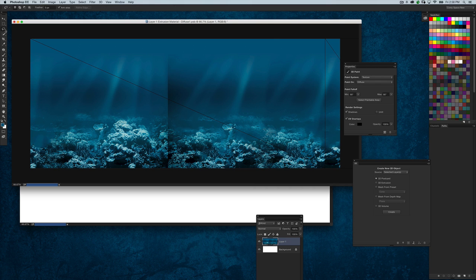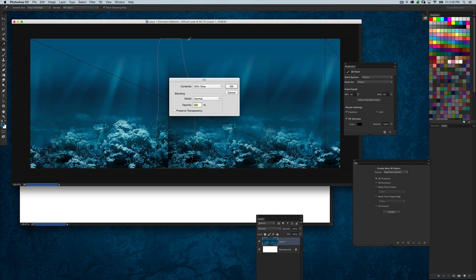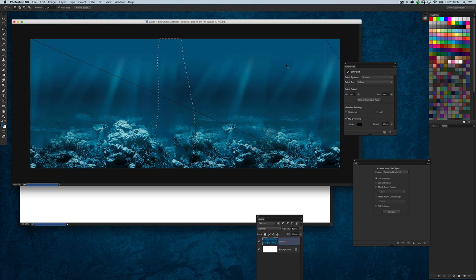So all we're going to do with that is just simply select that little area. And we'll just do a simple content-aware fill. And that gives us that little bit of the blend in there. Now you could go ahead and take the patch tool like we did a while ago and just modify it further if you wanted to. Just add a little bit there. Actually, let's get more like that. There we go. Select that area there. There we go. So now it'll appear much more seamless.